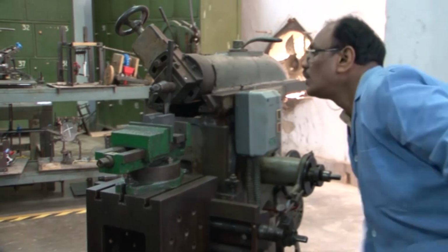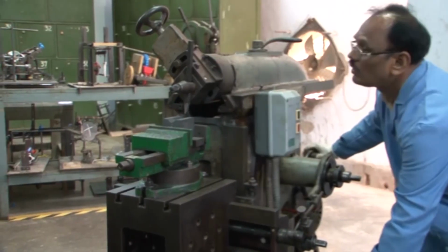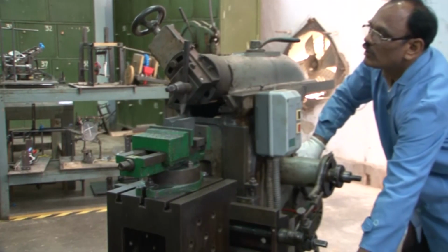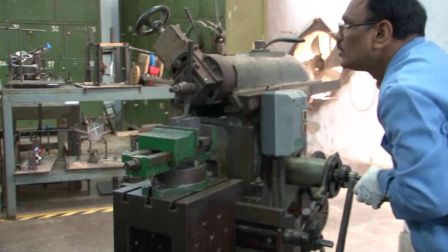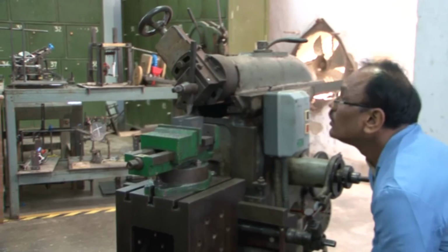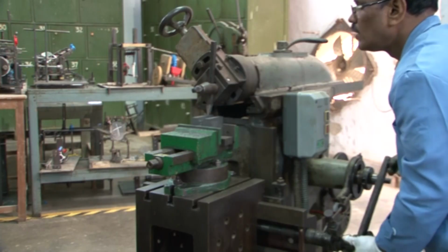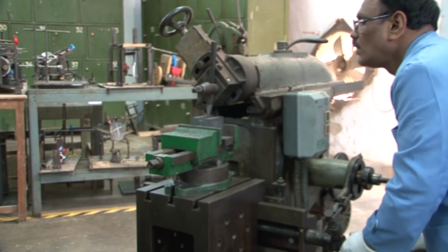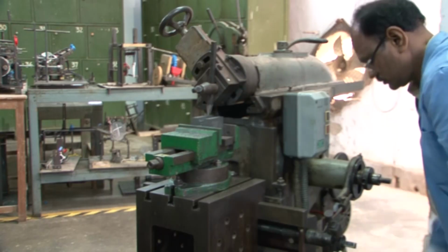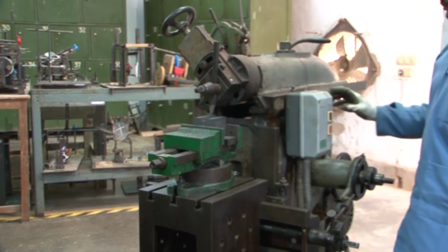Again, the tool is to be made in contact with the workpiece initially, so that the machine can be switched on and the operation can go on. That will be very similar to the surface that has been made on the right side of the workpiece. So, now the tool is in touch with the workpiece, after which the machine will be switched on and the depth of cut will be given to the tool in the vertical direction.